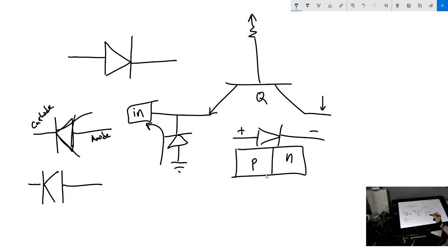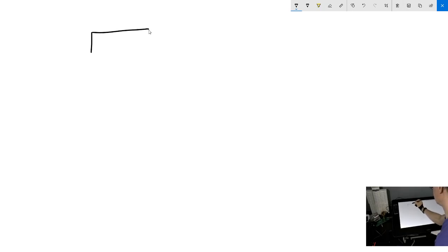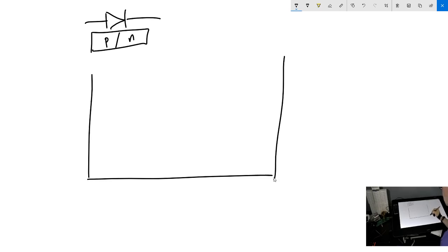Anyway, what I was getting at is that this is the structure of a diode. Well, you don't have a P butted right up against an N, right? Let me erase this, and PN diode. So if you have, and I'm going to draw a top view now. So here's your chip, and it's p-doped. So there are a few ways that you can make a diode. And typically, the P substrate of the chip is connected to ground.